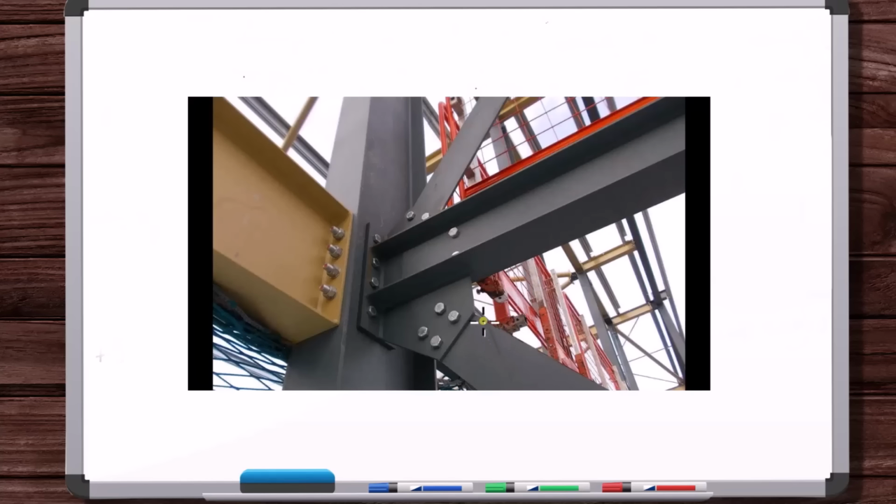If they wanted to, they could translate, this could move out here, this could move out here. The bolts are stopping that. But what if they didn't want to translate, and this just wanted to rotate here? Well, it can't do that because it's also bolted at the other end. But if you unbolted it at the other end, and unbolted this at the other end, then there'd be some friction, but you could rotate them based on this connection. You could change this angle without doing any translating.